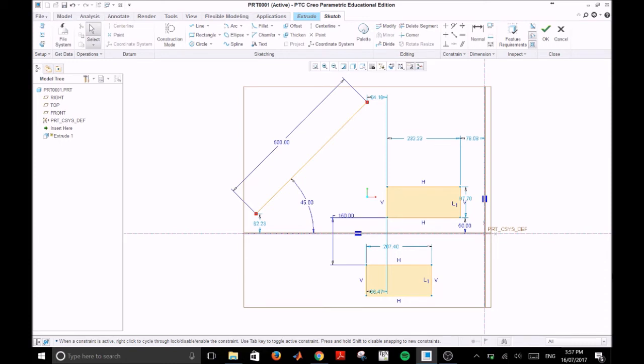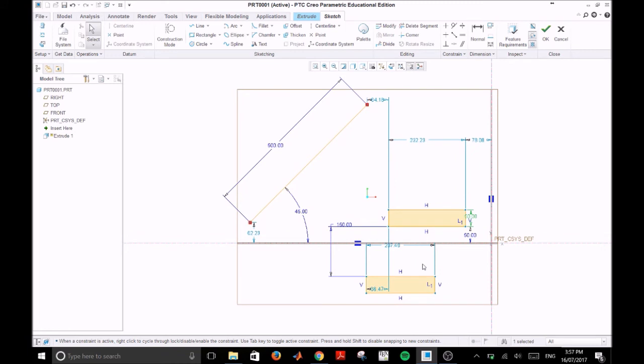The final thing that we'll look at in this video is using constraints. And this is a really useful way of locking certain features or dimensions to other features and dimensions. You may have noticed some of these, such as vertical or horizontal constraints, or length constraints, where length 1 is equal to length 2. So if we were to go in and change length 1 to say 50, the length 1 on this object would change as well. So this is often what we mean by design intent.